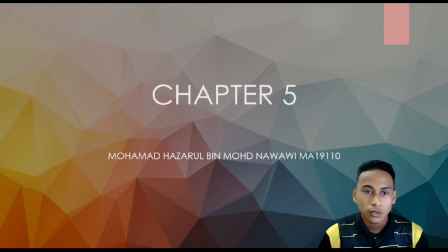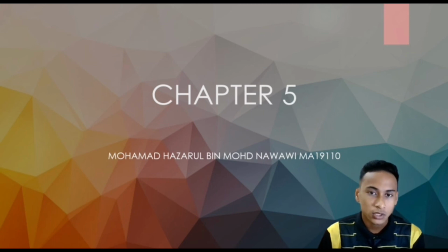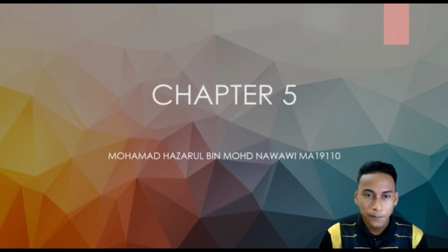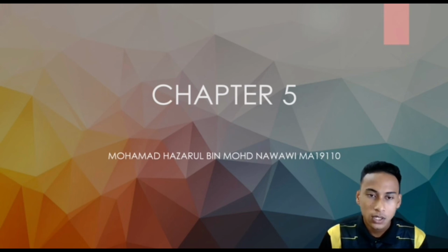Now I would like to present to you chapter 5, conclusion. In this experiment, we have finished designing a complete measurement technique for the fluid flow and the measure of the drag forces applied on the symmetrical aerofoil at different angles of attack. We also determined that the velocity distribution for flat plate boundary layer on the plane is generally affected by some factors, such as flow speed, Reynolds number, and the roughness of the surface.